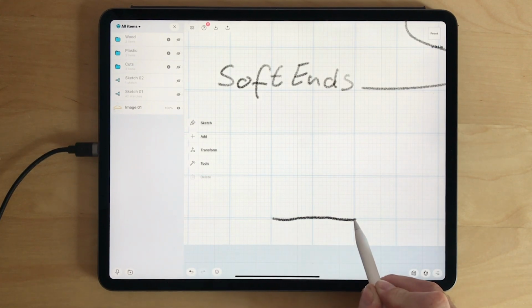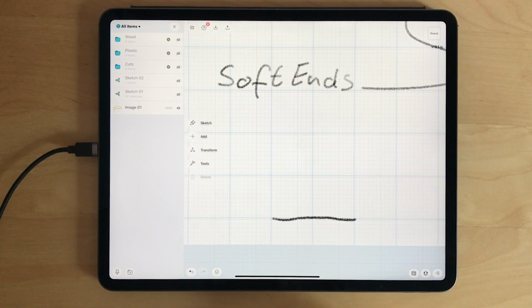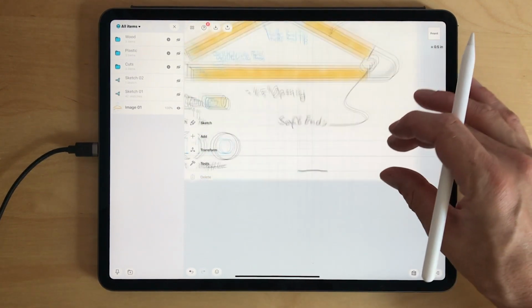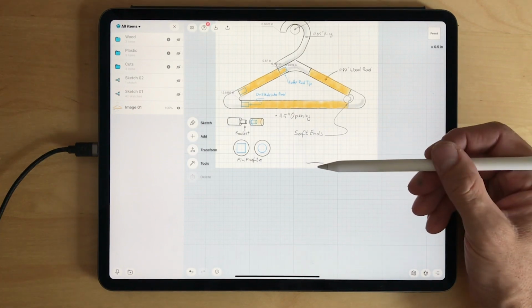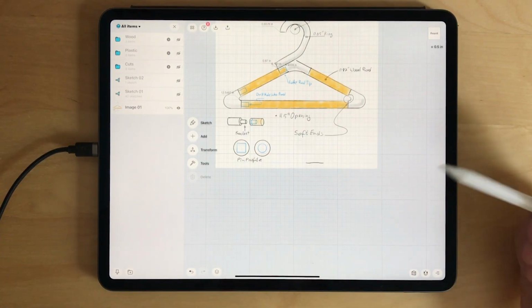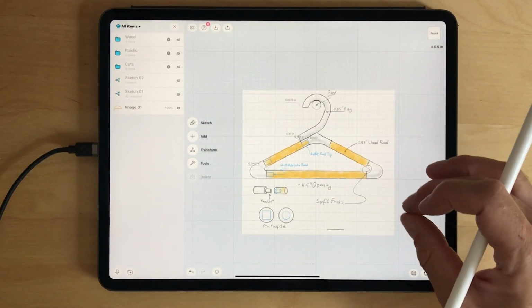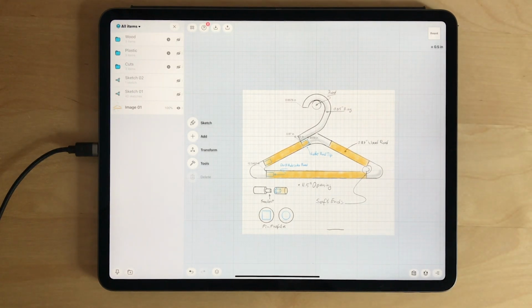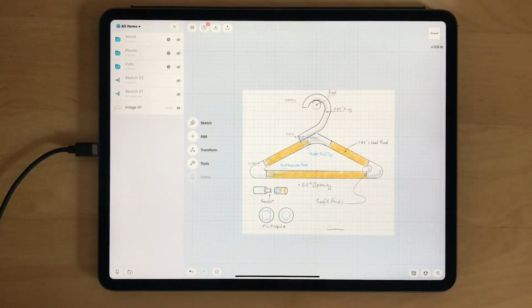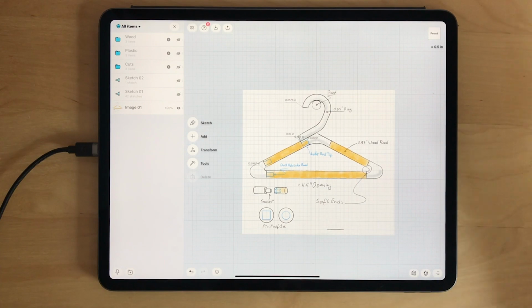This line is exactly, I think, 1 inch. Sorry, in Shapr I drew 1 line, 1 inch, and then I needed to scale that image until it fit my Shapr line. And this way I brought in a JPEG image perfectly to scale into Shapr.